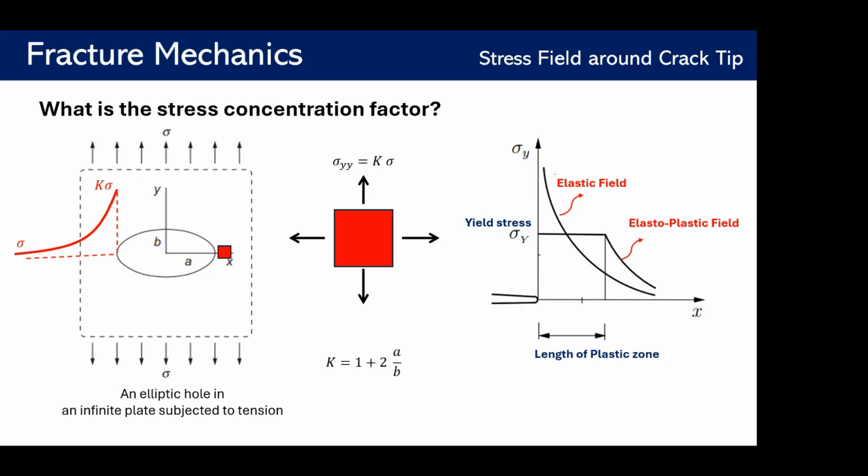So the distribution of the stress near the crack tip is depicted here. In a realistic scenario, it cannot happen because you cannot have a material that can resist infinite stresses. But theoretically, in brittle materials like rocks, glass, we can always assume this is somehow an accurate distribution of the stress. So this concentration factor is always infinite in fracture mechanics.